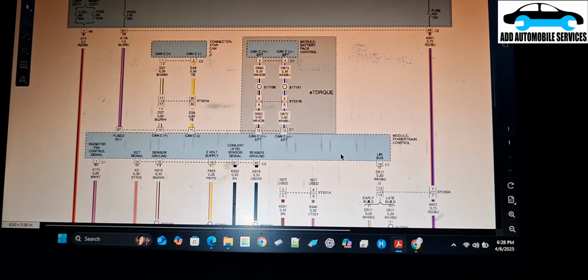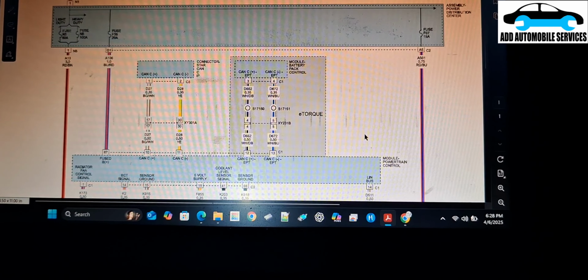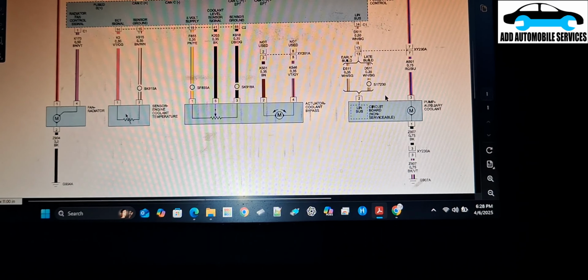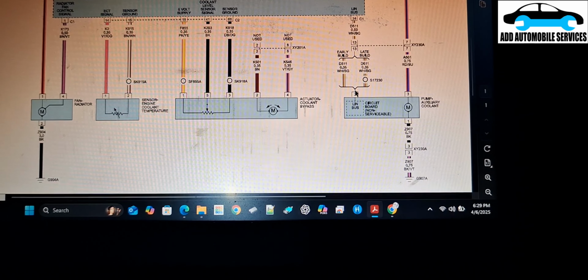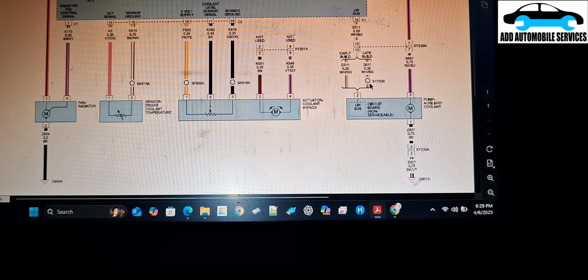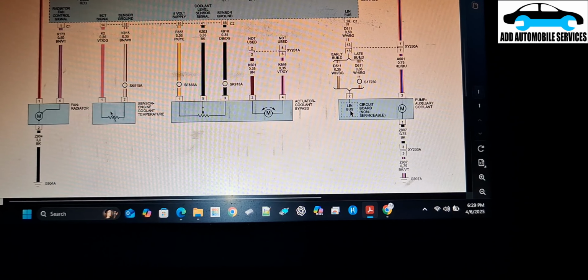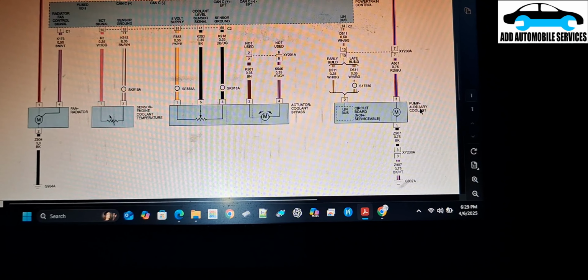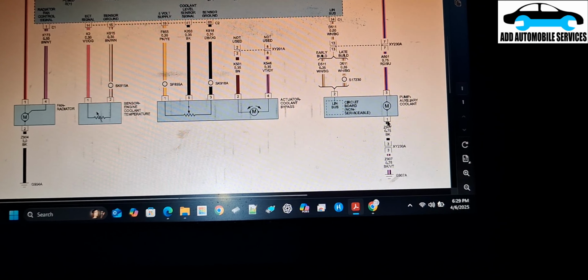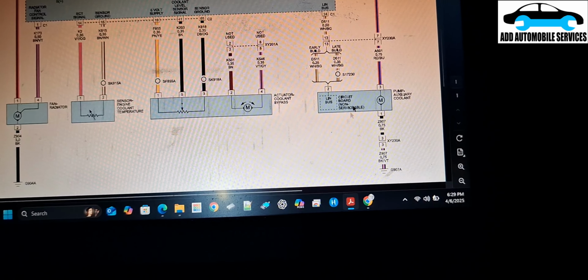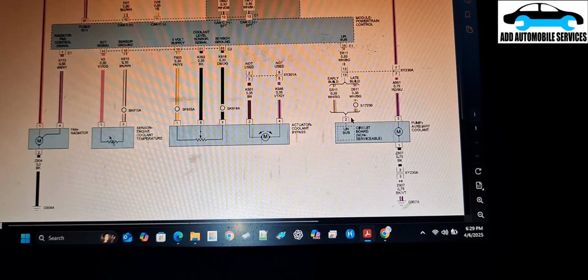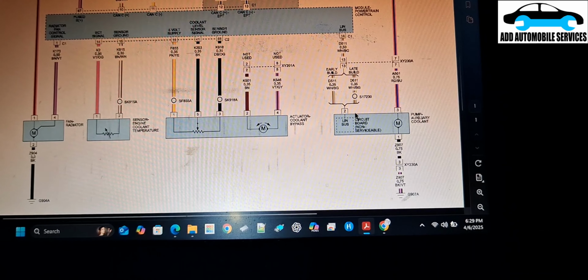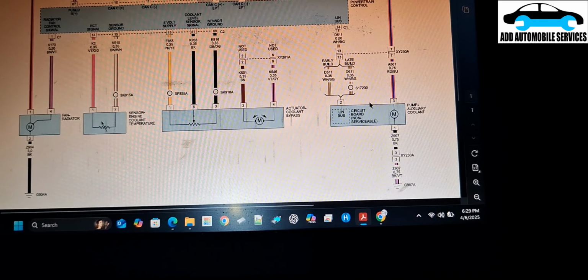From the OEM diagram, you can see this is the fuse box and this is the control unit, right? So it tells me that on pin 2, which is brown and white, I should be getting a LIN bus communication on the auxiliary pump, coolant pump. And I think this is why the control unit is able to identify that there is an open or closed circuit. So from this, pin 2 is the middle pin, as we've seen.